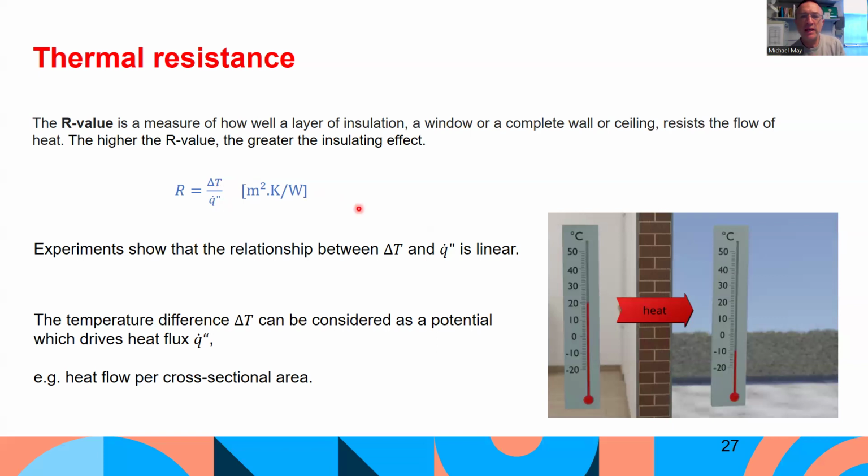So for example, if your home leaks a lot of energy and you want to do something about it, but it's too expensive for you to go insulating and wrapping the house and doing the roof and changing the windows and the doors, one other measure you can do is to bring in heating controls and regulate the temperature of your house at maybe 18 or 19 degrees rather than letting it go up to 25 degrees, because you'll conserve energy in the home much better if the inside of the house is at a lower temperature, because there's less potential pushing that energy through the wall.